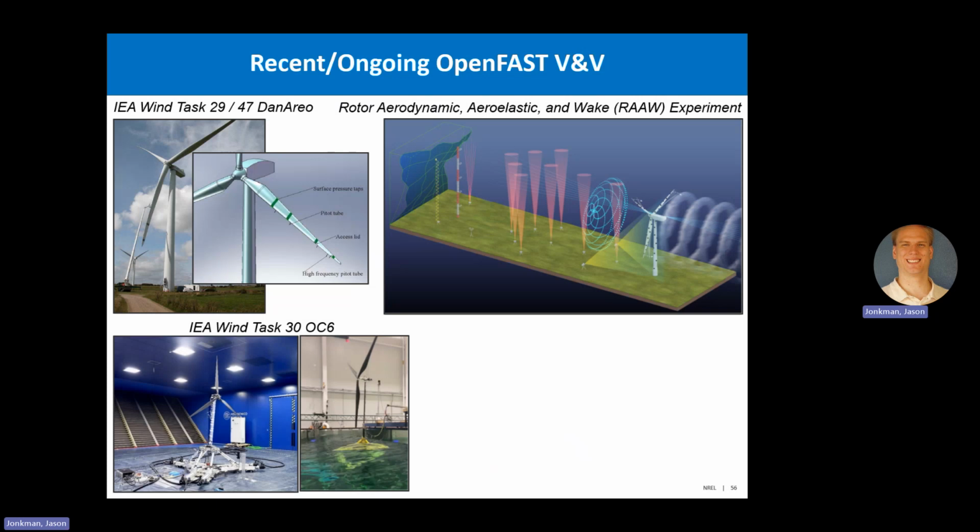For offshore, a couple of things have happened recently. There was a nice wind tunnel test at Polimi in Italy that we did some great work on for floating wind validation, where they had a shaker table, with the rotor surging and pitching in the wind tunnel. And we just said, well, how does our aerodynamics model work if the rotor moves like this? And actually, we were quite surprised it worked quite well.